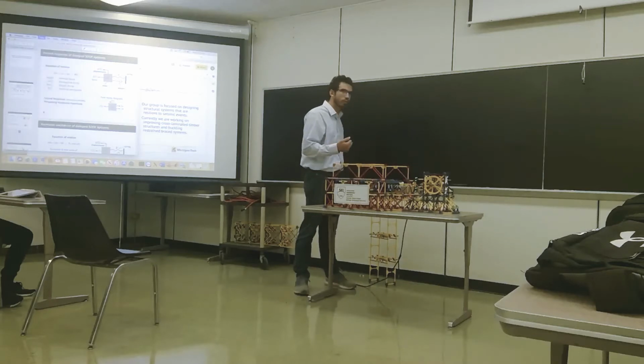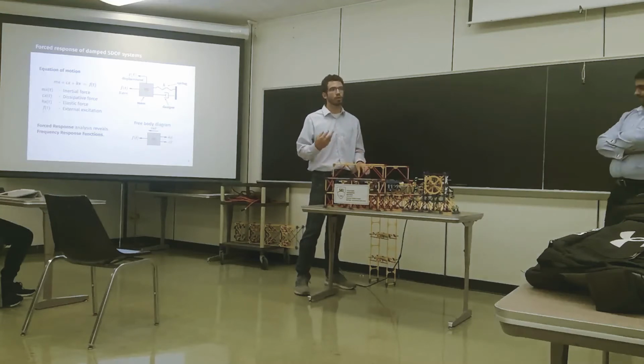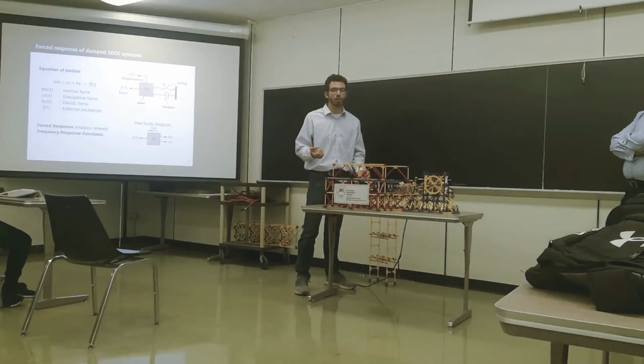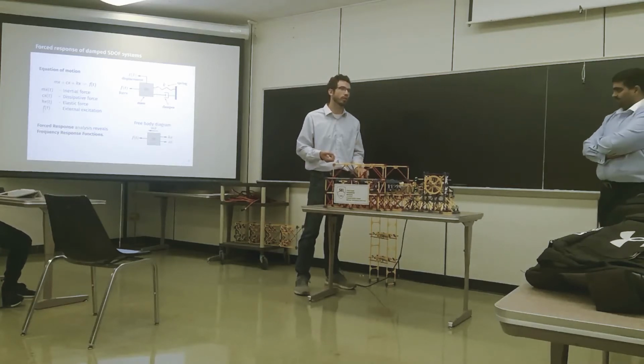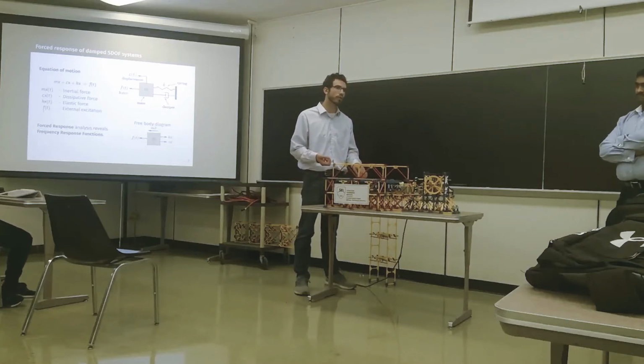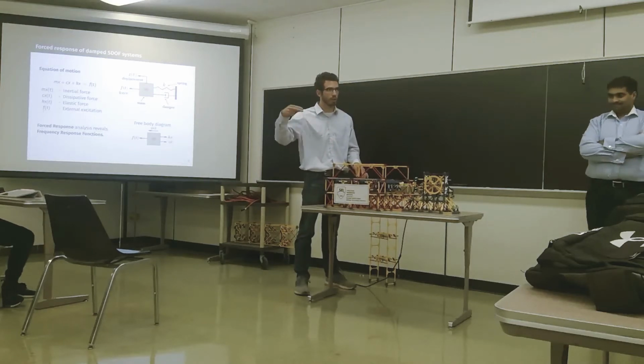What I showed with that building was if you have excitation of the structure and you yield the members. In steel, it's usually yielding that's going to cause that. And with concrete, sometimes you can have the opposite. Over time, concrete actually increases in stiffness to a certain point before it deteriorates, because it's a chemical process. It cures, and it increases strength over time.